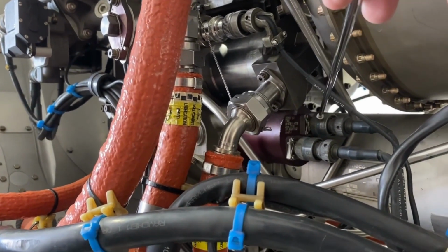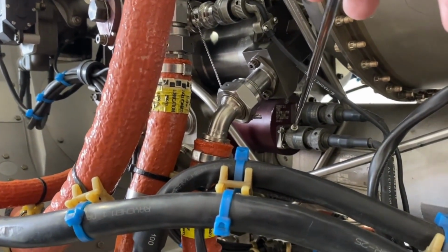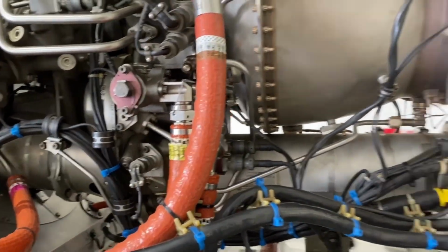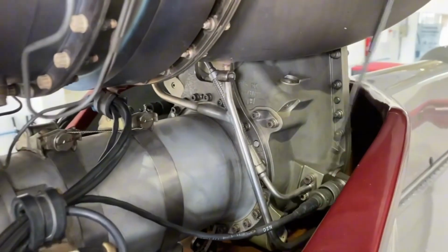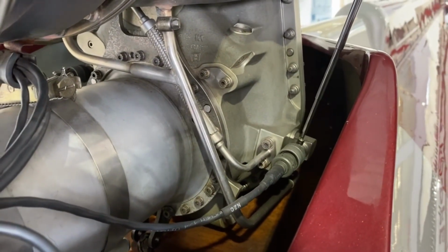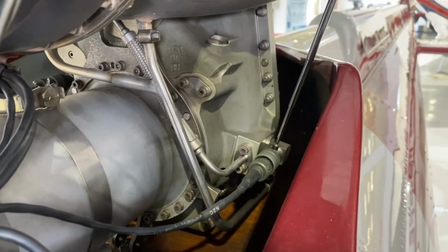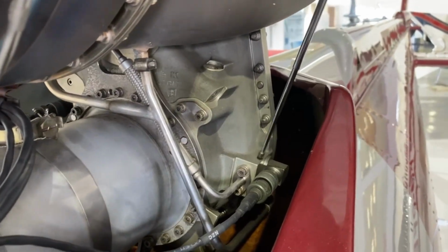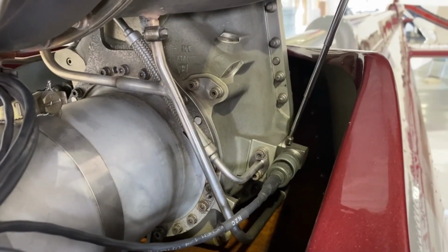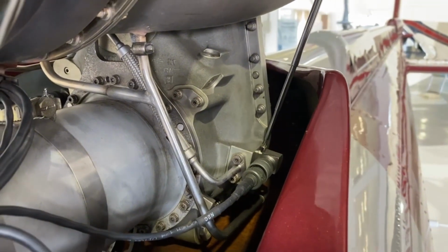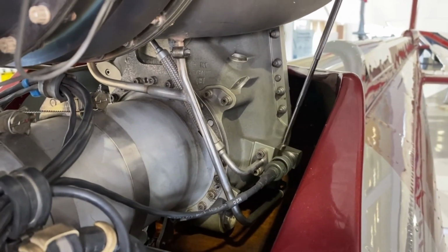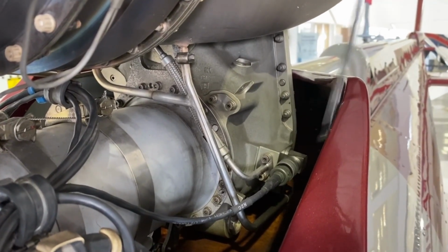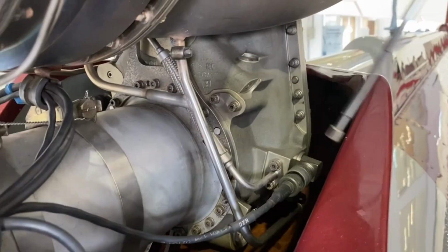The N2 rotation for the FADEC, which are N2A and N2B, and as we'll see, there's also N2C here, which provides the power supply. The other transmitter that the engine has for the FADEC is back here. This one is the N2C. This signal here is also a gear. It counts the magnetic pulses from the reduction gearbox gear to provide the FADEC with information about the N2 rotation. In this case, it would be the N2C. The N2A and N2B are on the other side of the gearbox, which we are going to see now.